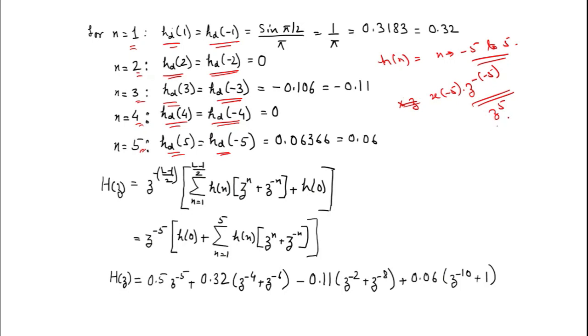So is there any operator to implement that? There is no operator to implement this one. So to avoid this condition and to make the filters realizable, we have to convert these HN values where n will be varying from 0 to 10, or if you want to generalize, 0 to capital N. Are you getting my point?